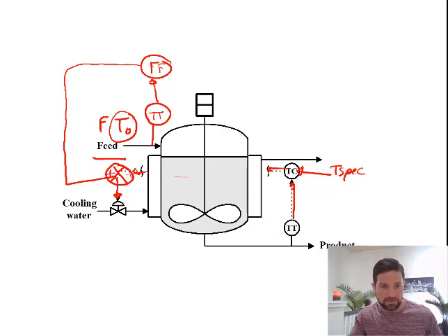So for our feed forward system, we would just combine the signal from the feedback and the feed forward loop. So if we think about now how this works, when the temperature of the feed doesn't change, the feedback control loop is going to open or close the valve. So this signal will be 0 and all of the action will come from the primary control loop.